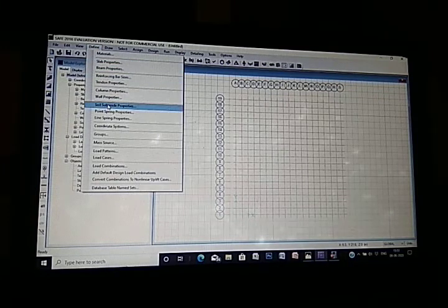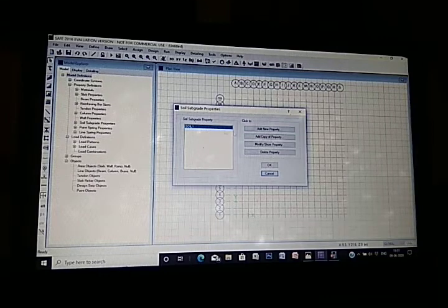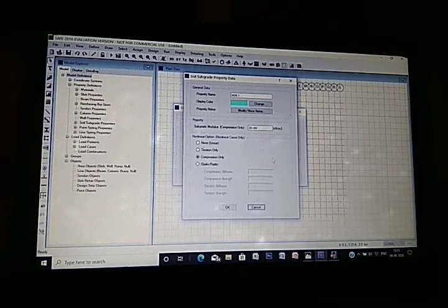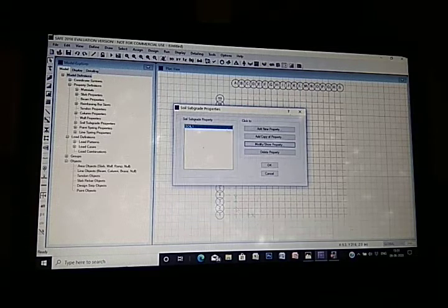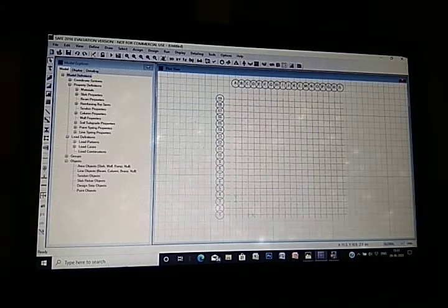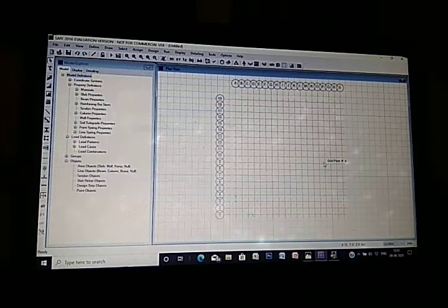So now soil, subgrade, open soil. So soil 1 we can modify it. So where it is 2e, we will need to make it 3e as given. Okay, so now we need to define load pattern. So there is a given dead load, live load. Okay, click on OK. We need to check load case. So dead load linear, live load linear, click on OK.